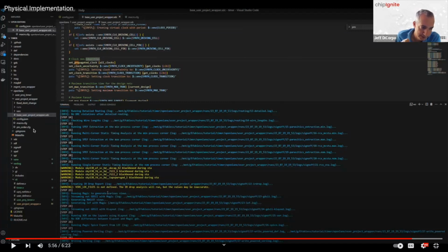There's also the pin order, where you can optimize the pin placement, especially for your sub macro as you consider how it gets wired up and routed in the top level. You can configure, adjust and update the pin order and placement for each of those pins.